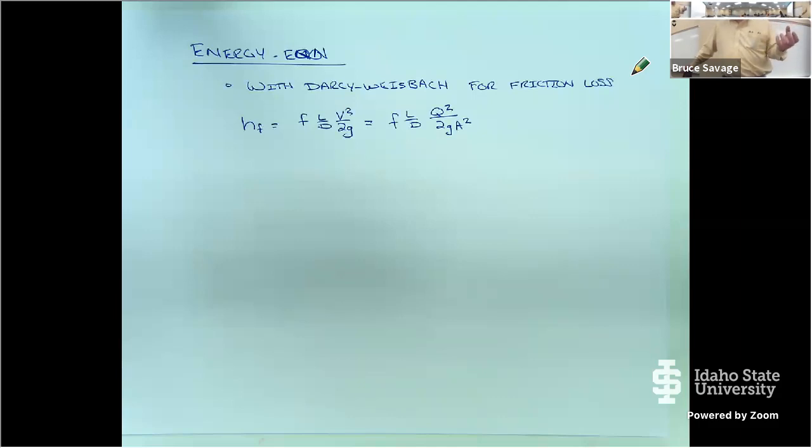And what are we talking about as large? Well, that could be a 4 foot, a 6 foot, or whatever. And sometimes the difference is very small, especially if you have a lot of elbows and bends. But if you have a long straight pipe, the theory breaks down. Does that mean our theory's wrong? Well, yeah, it does, doesn't it? It means there's something going on that we're not accounting for. When we did a dimensional analysis in fluids, when we did the modeling, the Buckingham pi theorem, there's something we missed. Otherwise, the equation should work correctly.